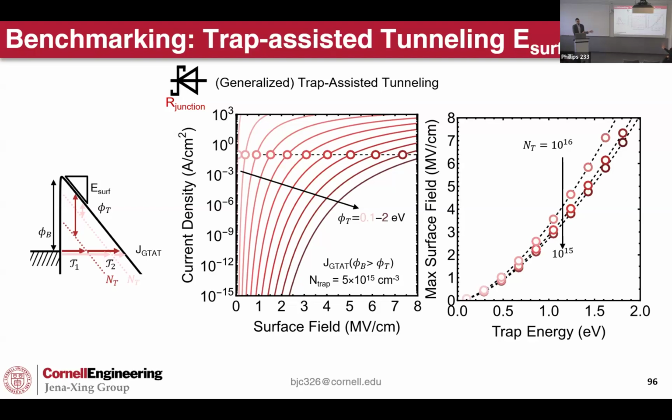Wait. First of all, in this chart, which corner is the desired corner? The very first thing is which corner represents where I want to be. Yes, ideally in the JE on the left, you want to be in the bottom right. Can you point it out? Ideally, you want to be down here, but that effectively implies extremely high resistance. Of course, in this case, this line demarcates what's governed by this tunneling mechanism. But ideally, you want to have as little current as possible.